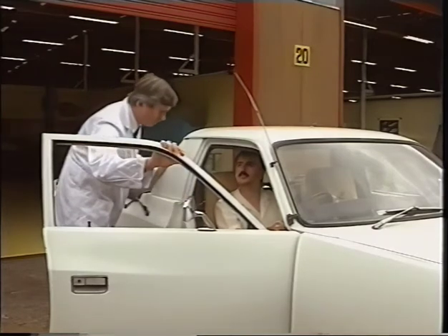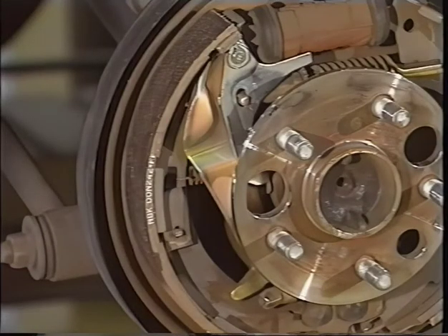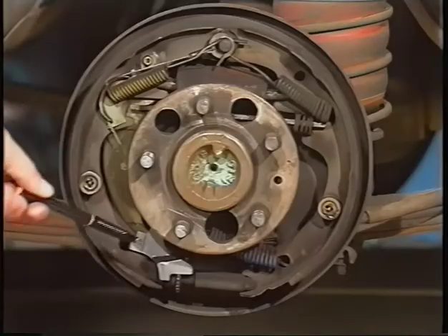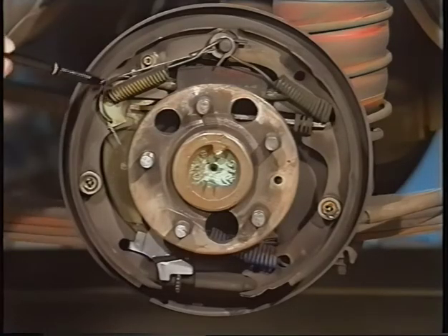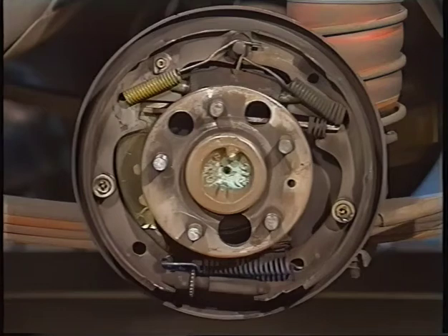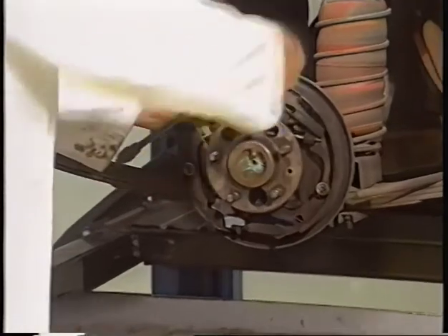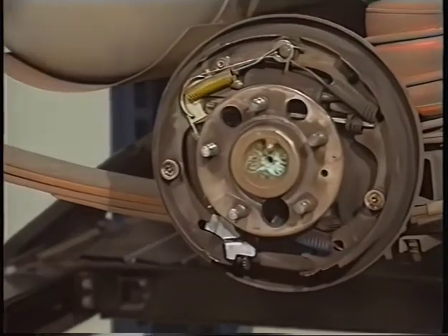problem. However, self-adjusters can also bind in the threads, or the handbrake cable can be adjusted to a point where the adjusting lever is held away from the adjuster teeth. In some extreme cases, the self-adjusting mechanisms may be prevented from working or have been removed completely by misguided service personnel. Should this be the case, the only long-term solution to the problem is to refit the self-adjusting mechanisms.